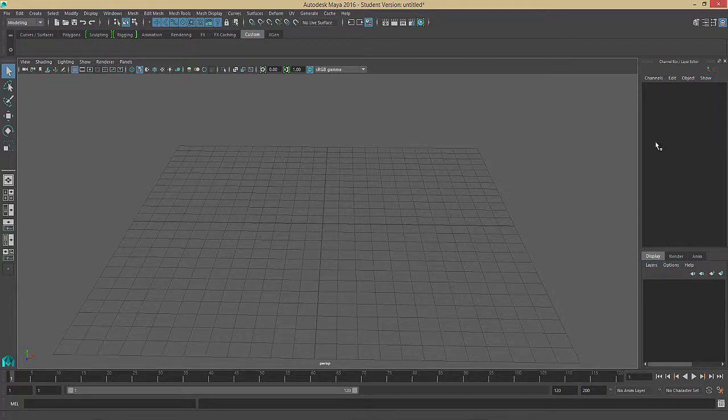Now another window that is here in the right side panel that will show up is your attribute editor. The attribute editor gives you more of the surfaces or selected components attributes, such as color, display properties, size, rotation, position, all these types of things. And the way that you view that attribute editor for the first time is doing Control A. So if you click on Control A, the attribute editor should pop up.